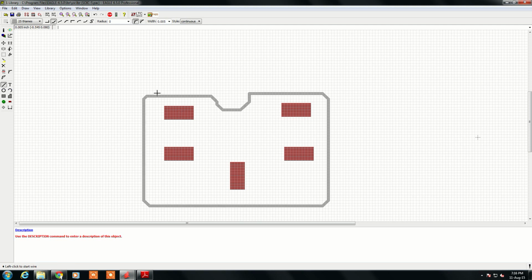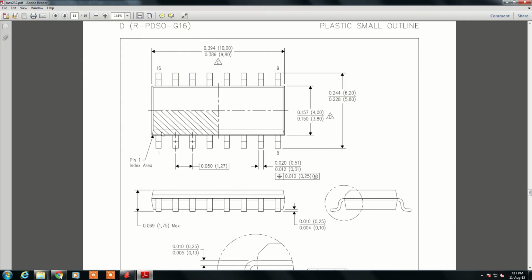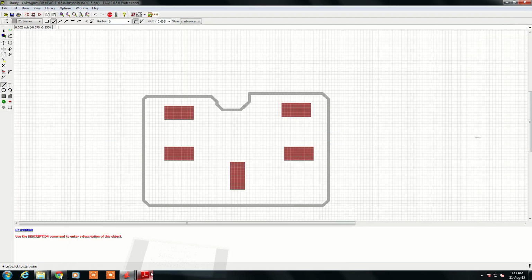You can do that. This doesn't have any significance, just leave that much space so that one can understand the size of the IC; at least this much space you should leave. But otherwise, what is important is the width of the pad, the length of the pad, the distance between the pads, the distance between left and right, top and bottom. This matters a lot, which is exactly as per the mechanical dimensions of the data sheet.